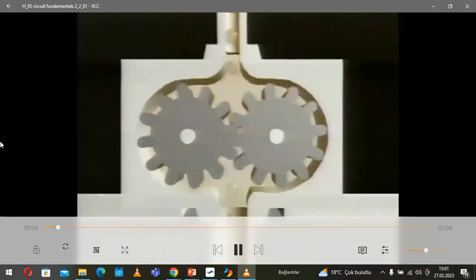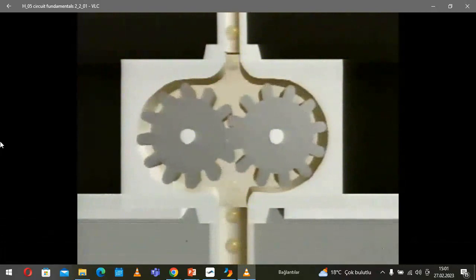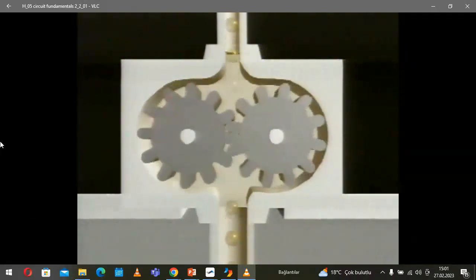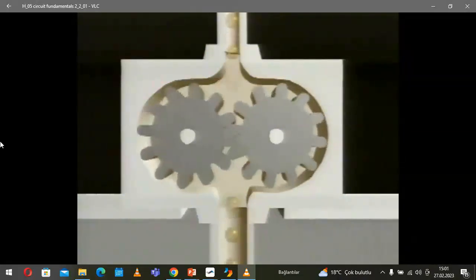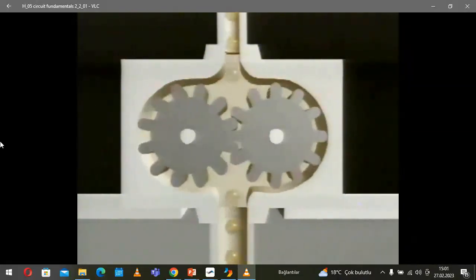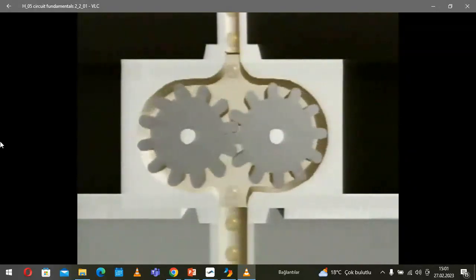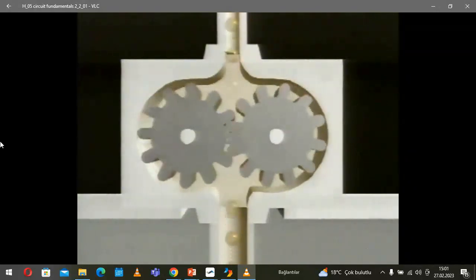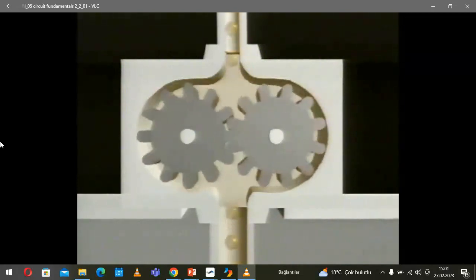This hydraulic pump is an external gear pump. This is how fluid flow is created. The suction chamber is connected to the oil tank. When the two gear wheels turn, the volume of the chamber increases slightly whenever a tooth leaves a gap. This creates a partial vacuum in the suction chamber, which then causes the oil to be drawn out of the tank.